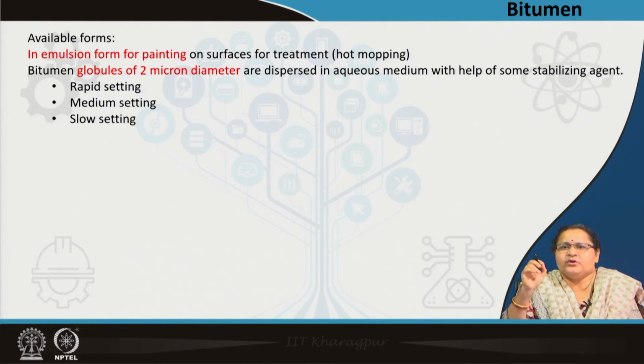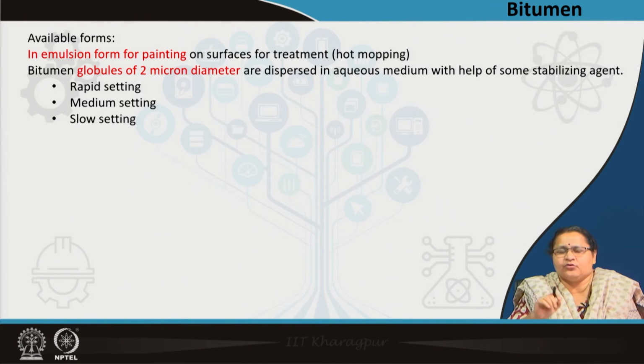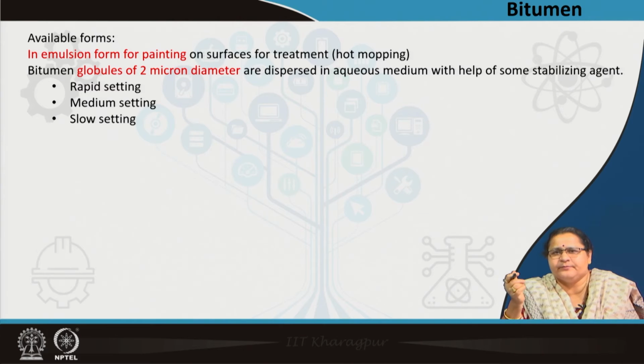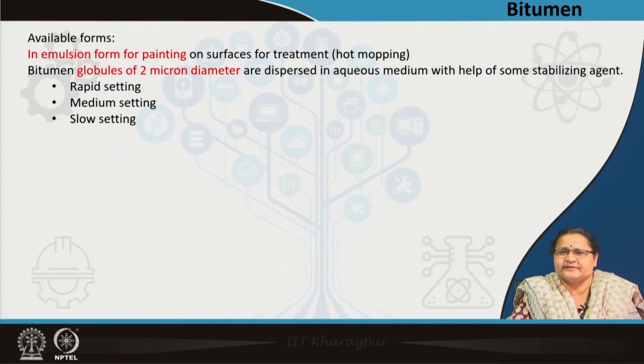It is globules of bitumen, say around 2 microns in diameter, suspended in an aqueous medium, which has a stabilizing agent added to it, and this aqueous medium helps spread these globules, and it eventually evaporates.